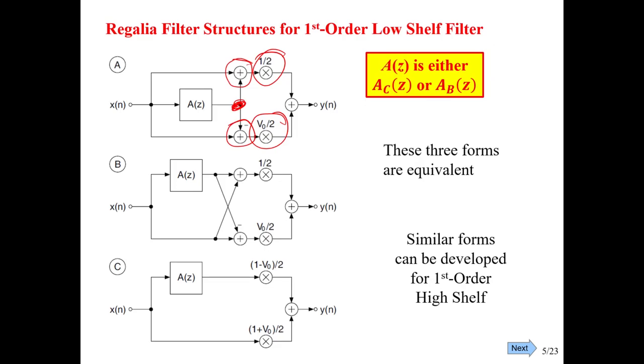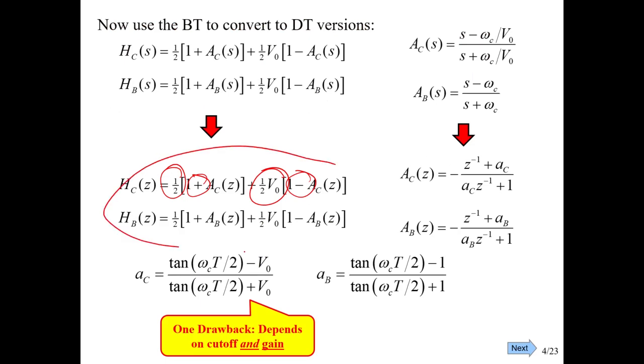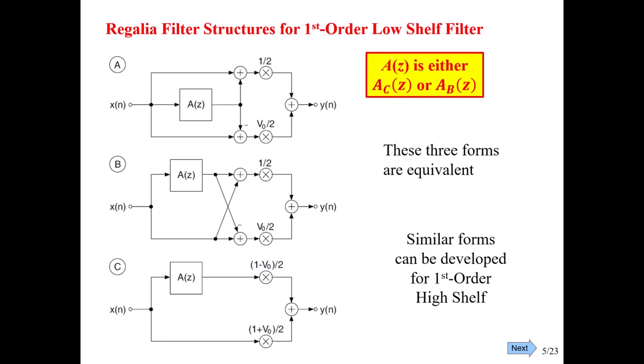So you should be able to convince yourself that once you add those two things together, that in fact does implement that. And so now to switch between cut or boost, we just have to change the two coefficients in there. Well, really just one, AC or AB, but it just shows up in two places in the transfer function. Now, we can come back here and do some algebra to get that into a slightly different form, but we can also just trace our way through here, right?